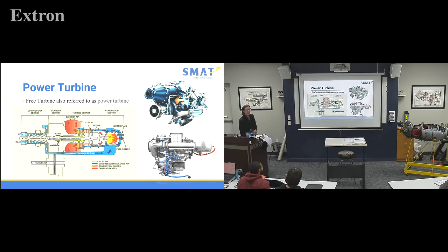Can you go through which turbine controls the compressor and which one controls the output? Yes, our N1 is more the high pressure one, you could say, because this is the one getting immediate heat, or energy, right off our combustor. That one is going the whole way through to our compressor. And then the next one is our N2, which is this outer one coupled down to the output shaft.